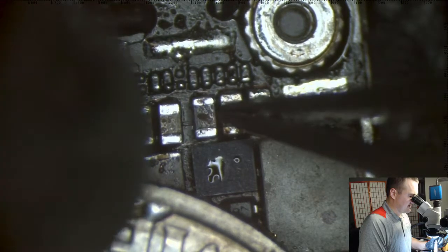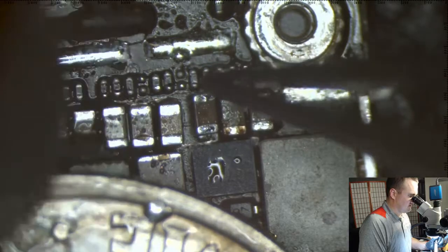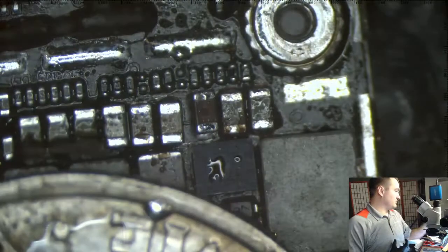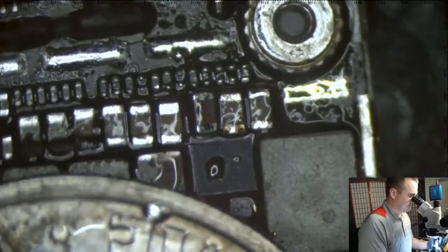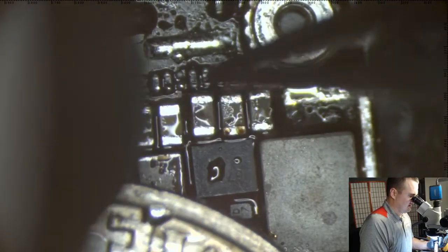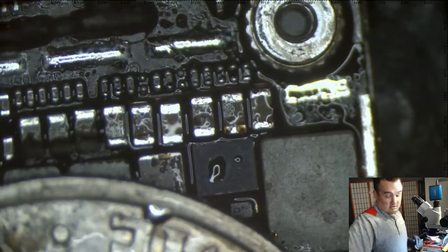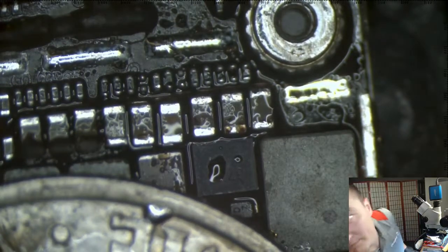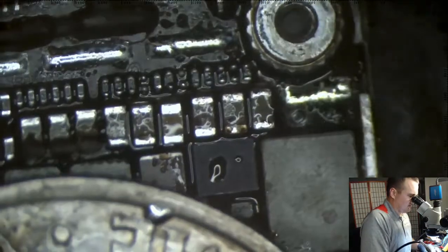If it was just audio IC, yeah, I'd probably test drive an iPhone 7 and carry it around. The bigger problem that's much more scary and sucks for repair shops and micro-solderers is the baseband CPU. Might just decide today's the day. It might just up and quit on you. There's no predicting it, there's no preventing it, and there's no fixing it. You get an internal short inside the baseband CPU, phone won't even boot anymore.